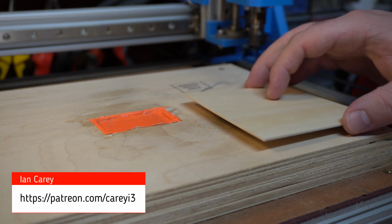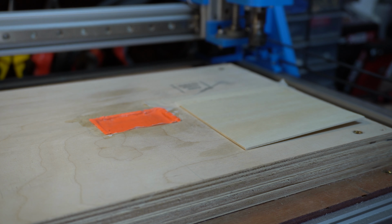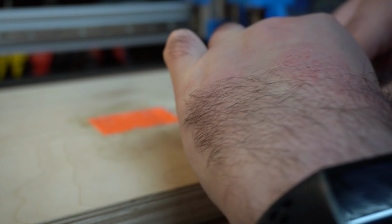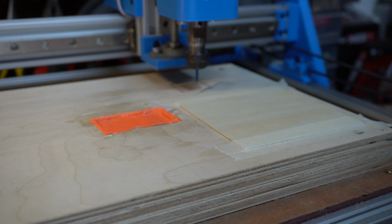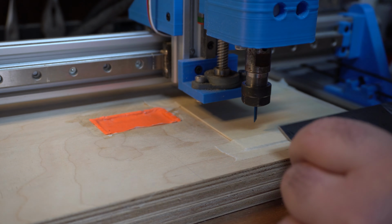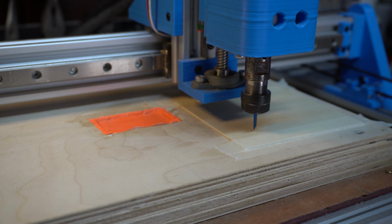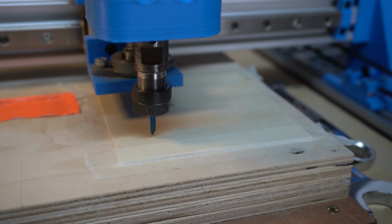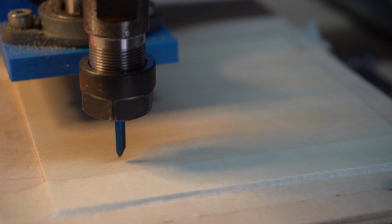Onto the actual engraving now, and because of how light duty all this work is, a fixturing method of just taping everything down works absolutely perfectly here. The algorithm that generates the plan basically works on a 6 by 6 centimeter panel. These sheets are 10 by 10 centimeters, so the only thing I have to do is just find a point about 2 centimeters from the bottom left in both directions, X and Y, and that gives me my start position.